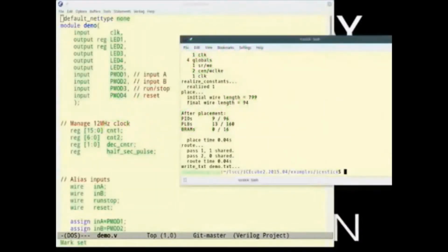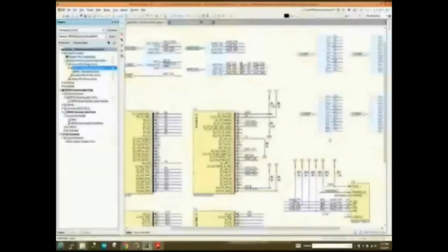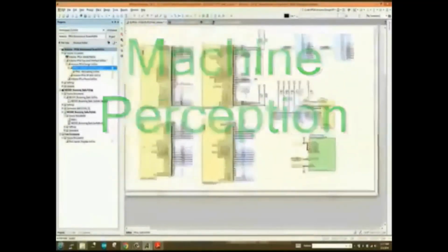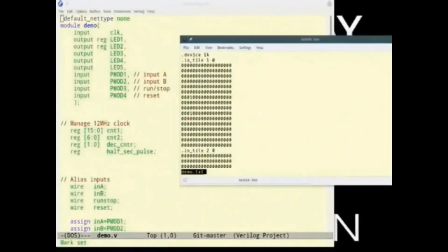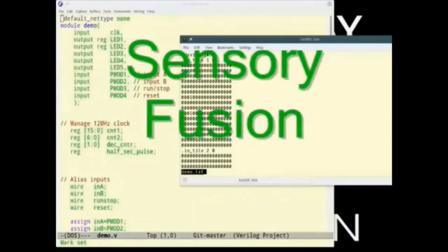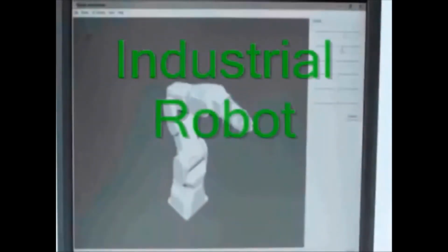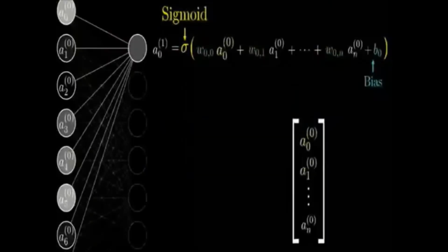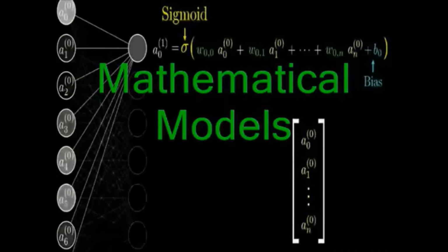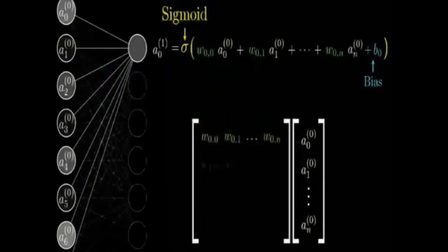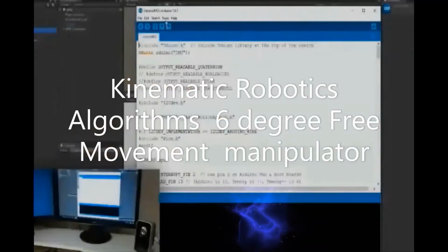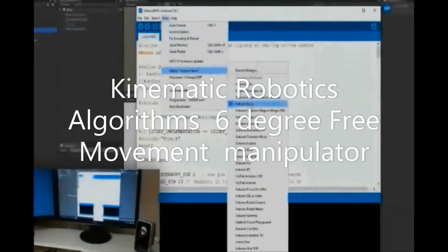The kinematic robotic is characterized by the use of algorithms of reading points of 3D space, floating interpolation by a polynomial of the 5th order, iterative process of solving inverse kinematics tasks, dynamic feed-forward torque of each motor, and calculation of position control algorithm with a control loop.